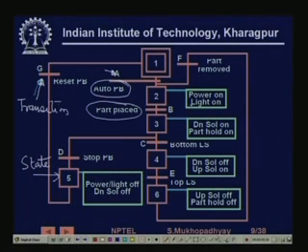On the other hand, these green rectangles indicate which outputs are on at each state. For example, in state 1 nothing is on, none of the outputs are exercised, while in state 2 the power and lights are on. In state 3 the down solenoid is on, this is the state when the solenoid is coming down. So, this is the initial state, here the system is switching on the power and the light and possibly waiting for the part placed signal to come. It might spend some time here, then it is coming down, so it takes time there.